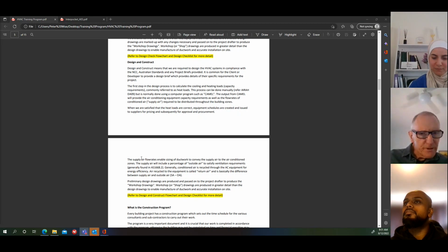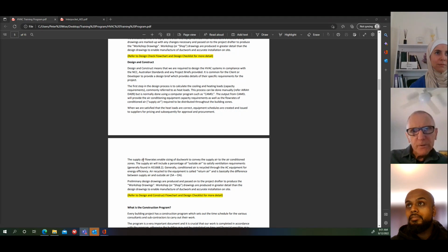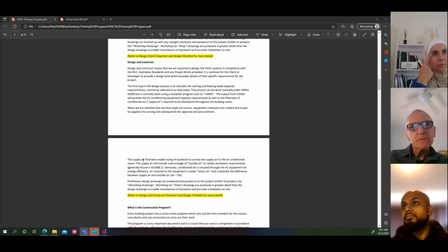And once you're happy that you've got the right answers, then we start the process of scheduling equipment again. Camel will give us the equipment capacities and the airflows that we need, okay? So there's two things we can do now. We can schedule all the air conditioning equipment, and we can schedule the fans. Well, air conditioning equipment, including fans, and there will be other fans. There'll be outside air fans, there'll be exhaust fans and so on. So you can work through that process.